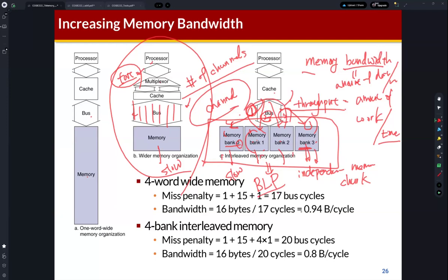It means we utilize multiple memory chunks to increase the performance of slow memory, right? DRAM is composed like this. Also the SRAMs like cache memories are composed like this. So we can utilize bank level parallelism or memory level parallelism to handle the slow memory. This is a very important concept. I hope you can understand this one.